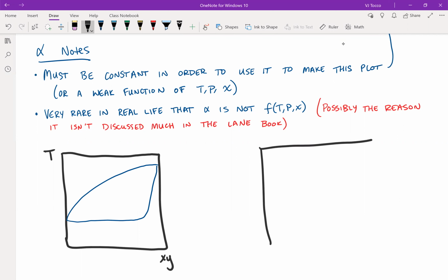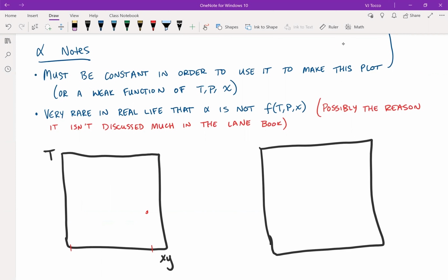You could convert simply by taking various temperatures, and it doesn't matter what temperatures you use as long as you do the entire range of temperatures, and you could read x and y coordinates off of this plot. I drew this TXY diagram in terms of the less volatile component, so I should have drawn it differently. Let me try again to draw it. Let's draw something like this. I know that it has to begin and end at the same point.